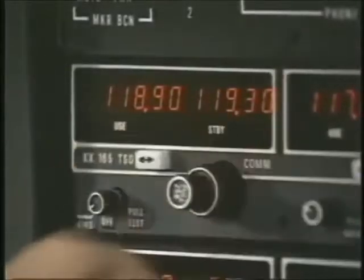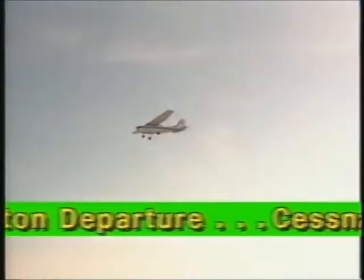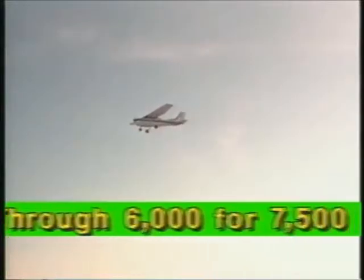Because you are being handed off from the tower to departure control, the controller is expecting your transmission. Thus, your initial contact is very brief. Sutton Departure, Cessna 62740, climbing through 6,000 for 7,500.